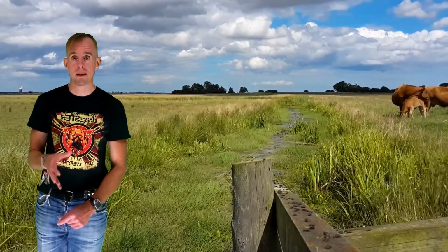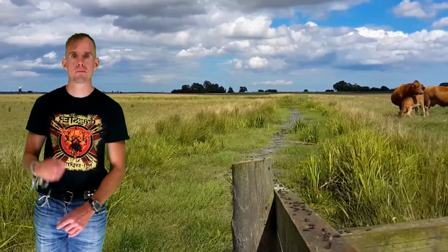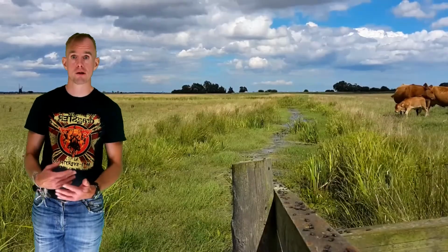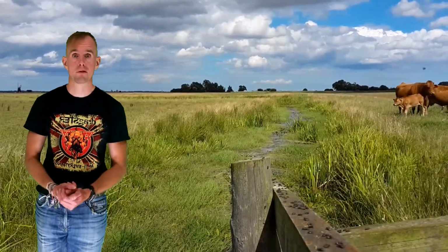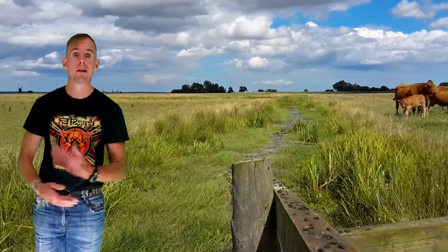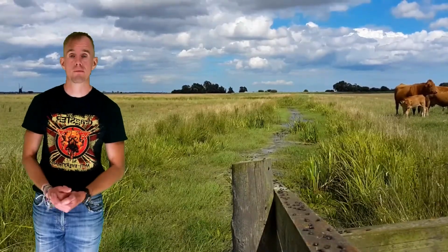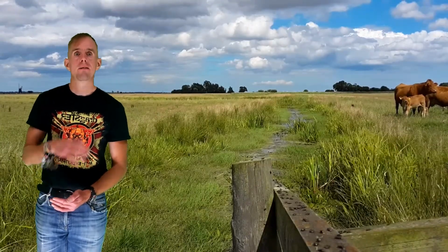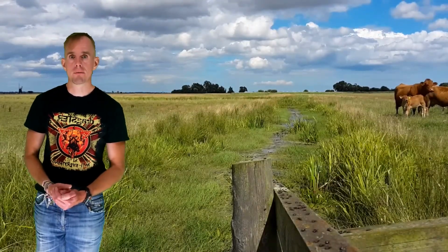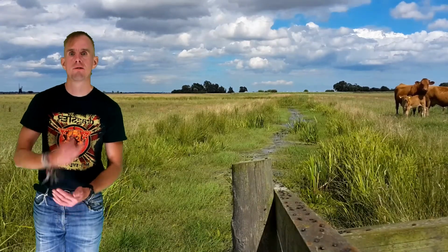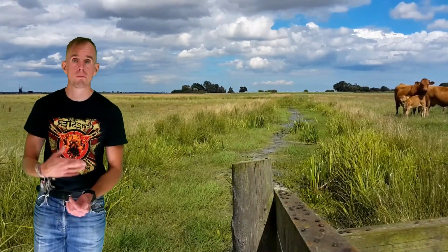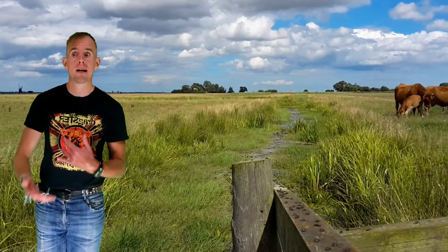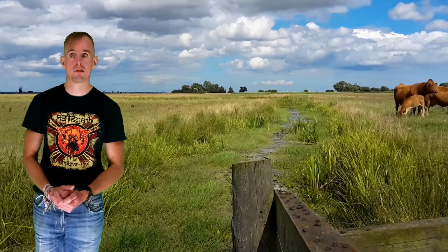Up until this point in lecture 16, we've looked at mechanisms of deformation and mechanisms of breakup, and we understand now that emulsions can exhibit both of these types of behaviour depending on the capillary number, the viscosity ratio and the deformation field. What we're going to do now is look at relative viscosity results and see how we can estimate the relative viscosity of an emulsion so long as we know something about the droplet size or droplet size distribution, the capillary number and the ratio of the two viscosities.